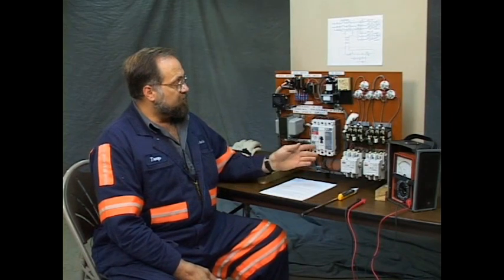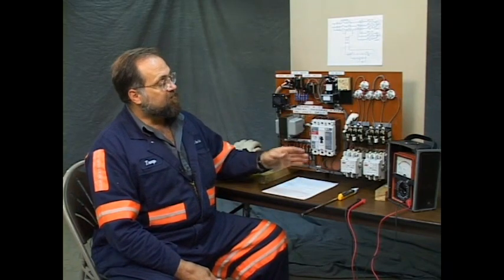The inrush of current to start the A motor would be at a level where if B motor started at the same time, the short circuit protection in the motor circuit protector, such as this breaker here, 1CB, would operate, would trip. So we need to stagger this start to keep the inrush to an acceptable level to where the main breaker could stay in. Now, the main breaker is sized for a short circuit. 2 motors starting would simulate a short circuit and would cause it to trip. Hence the timing. We're going to stagger this start.